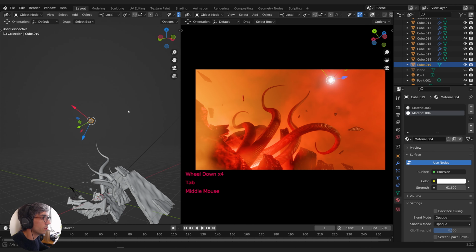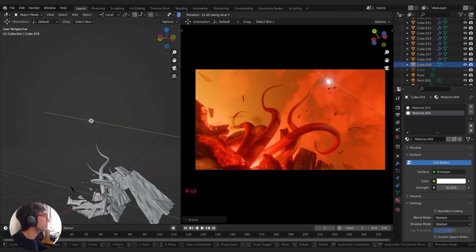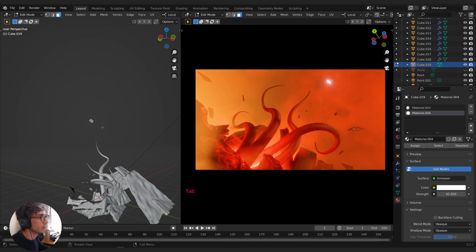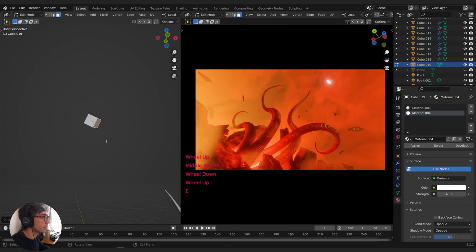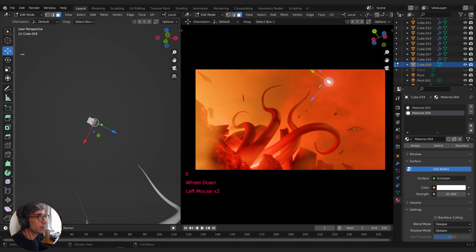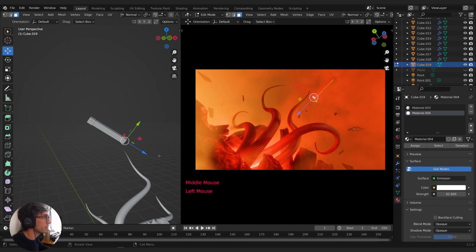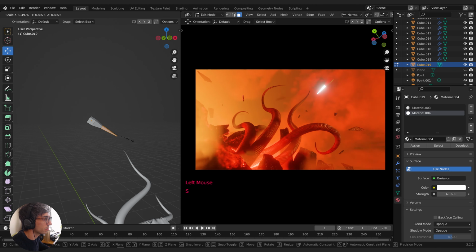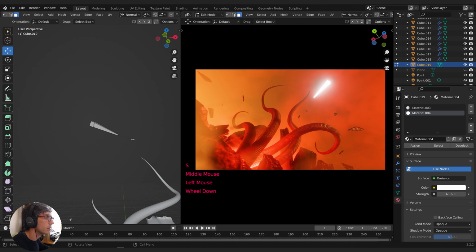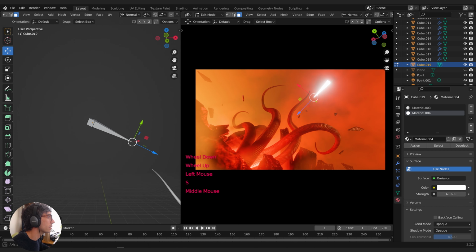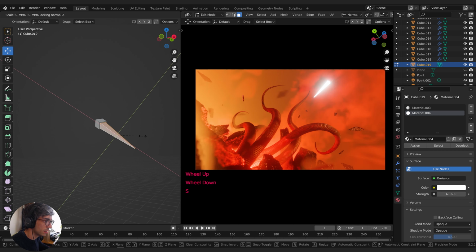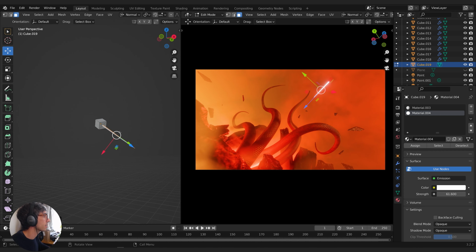And let's get it rotated. And then let's hit E to extrude. Grab my controls, set myself to normal. And I'll grab this out and scale it down. I'll Control plus to select all of that and assign the glowing shader to all of it. There we go. Scale that right down. Grab all these guys. I'm going to scale Shift Z. I can just scale that rocket bit.